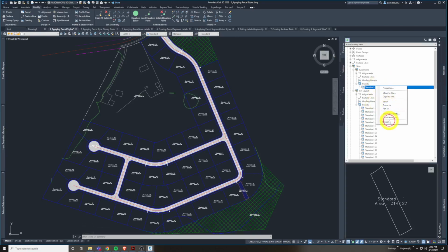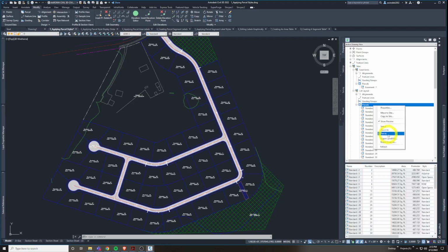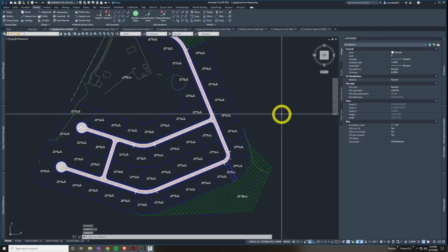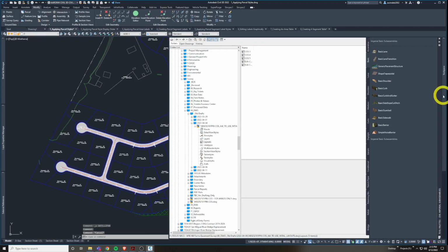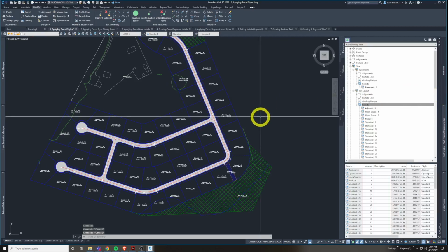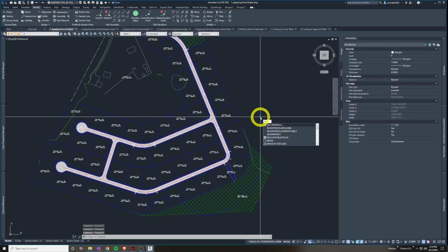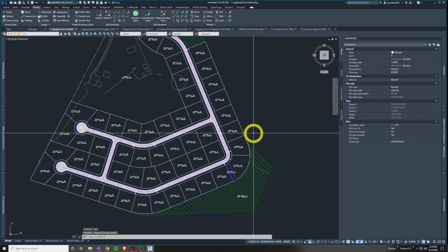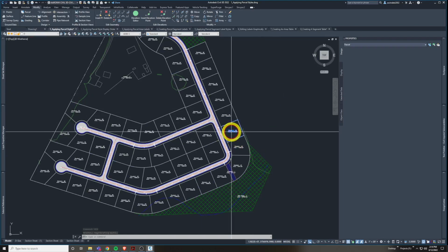And I'm going to refresh these. Interesting, Control Z did not work very well. That's a little bug there. But anyway, I changed them all. Let me try typing in regen all. There, I had to regenerate physically the drawing, which is kind of odd.